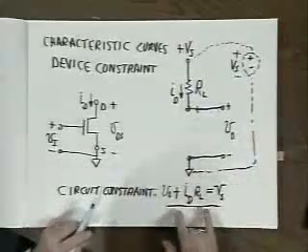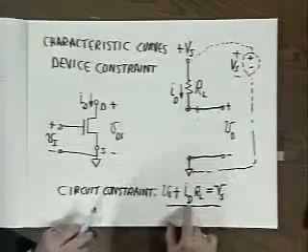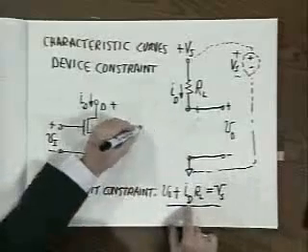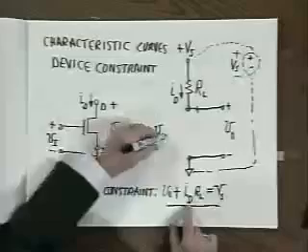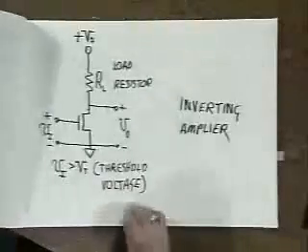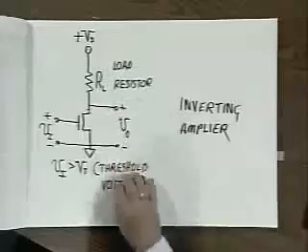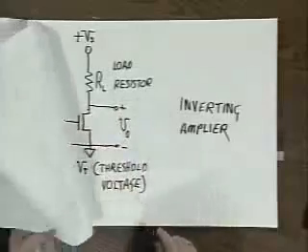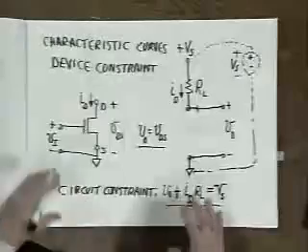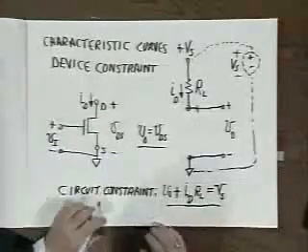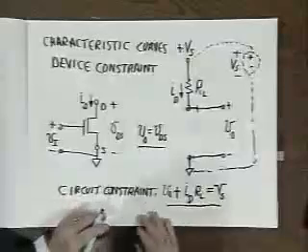Note that this circuit constraint is a linear relationship between V sub O and I sub D. Also, of course, V sub O, the output voltage, is just equal to VDS. That is, the circuit is constructed in such a way that the output voltage, as I've defined it here, is the drain to source voltage of the transistor. So this is an identity. Putting the two circuits back together then to the original amplifier gives us the complete amplifier.